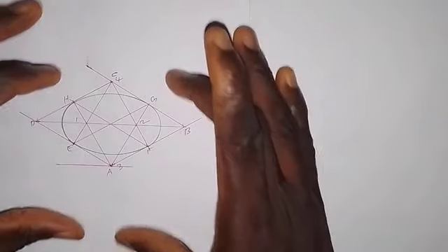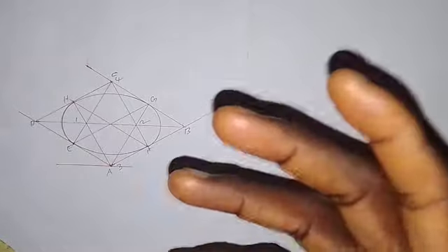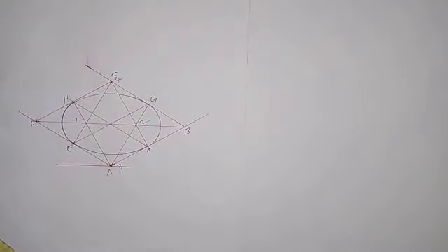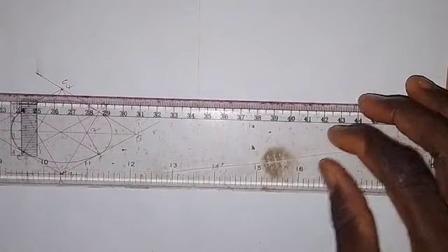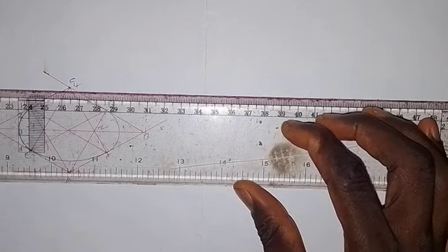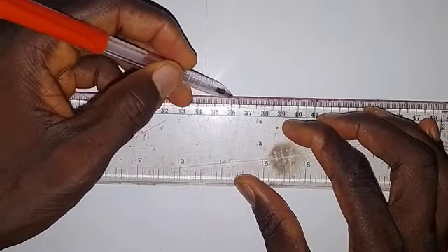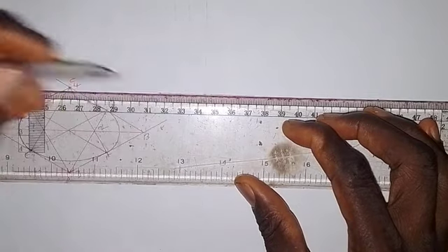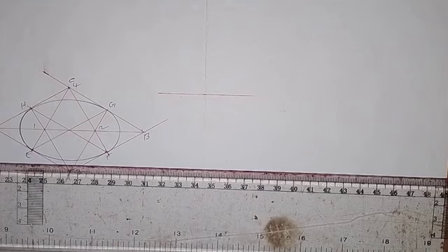So this is on the top face of an object. Now, let's look at that of the left side face of an object. If we are to draw on the left side face of an object, I'm going to come up here. We are going to draw a line here like this on the left side face. So we are to construct an isometric square here.